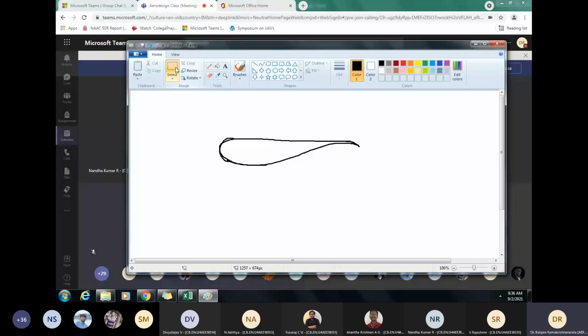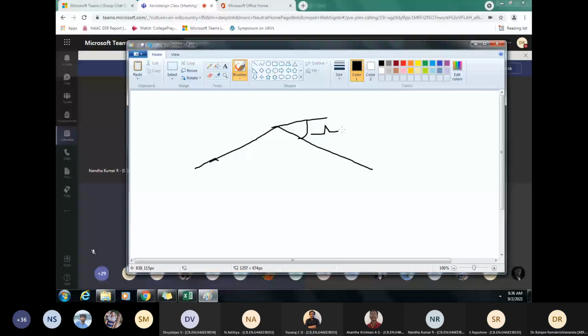First of all, you have wing sweep, correct? Leading edge sweep, right? So if you have a Mach number M here, what matters for critical Mach number is the Mach number component normal to the wing. This is the normal direction to the wing.